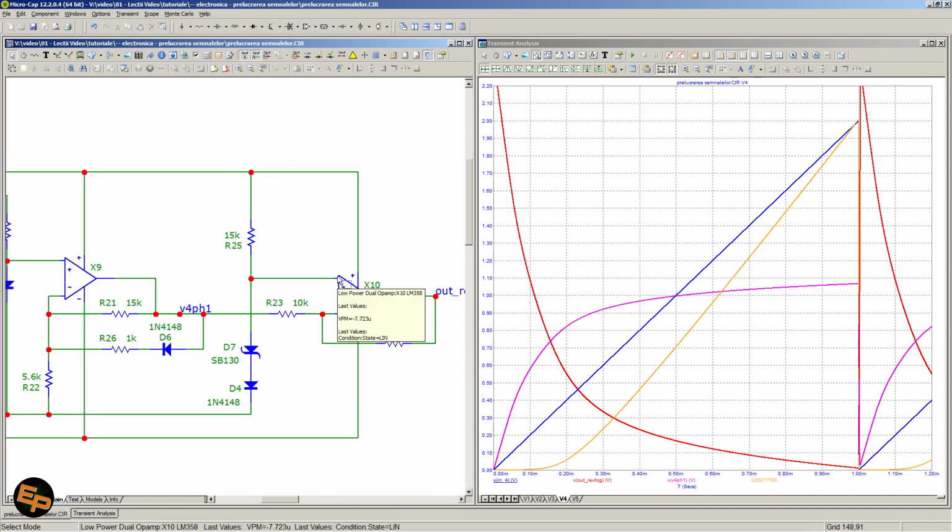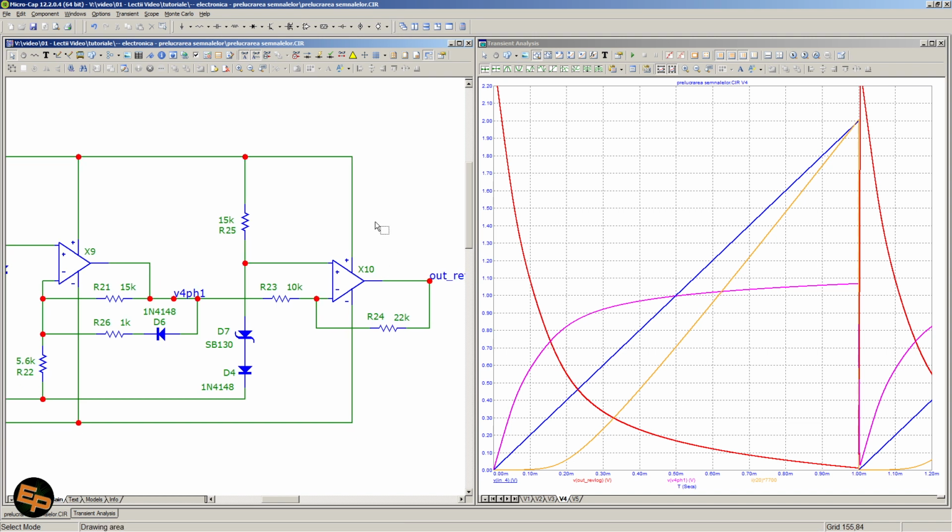And this voltage, I am placing it into the plus input of this second op-amp. And this is how, in the end, after 2 op-amps and this entire circuit, we have the red curve here in our graph that looks like this. That looks like the opposite of the purple curve, and also much bigger because we have an amplification factor, okay?